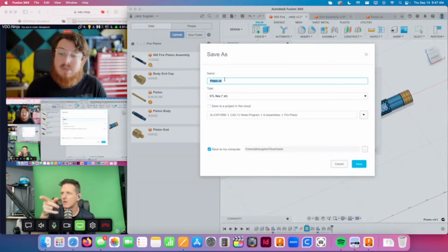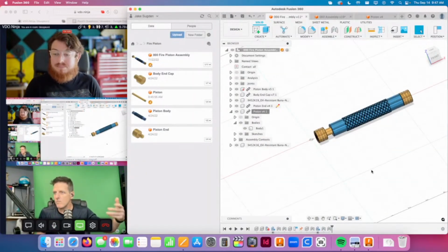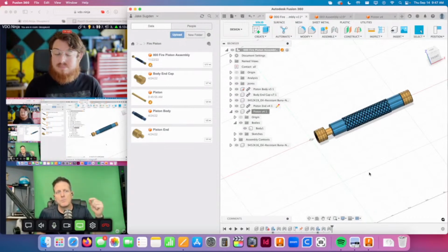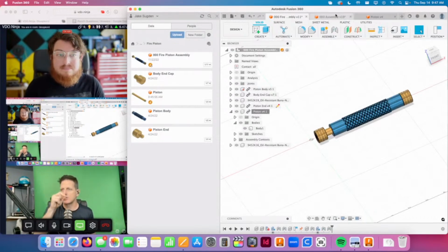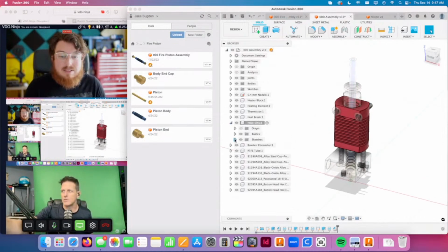There we go. What I was getting at is, when you're doing a model like your first example with the internal components, if you make a change to the component, you don't get revision history information about the changes to a specific subcomponent the same way that you do with what you've got here.